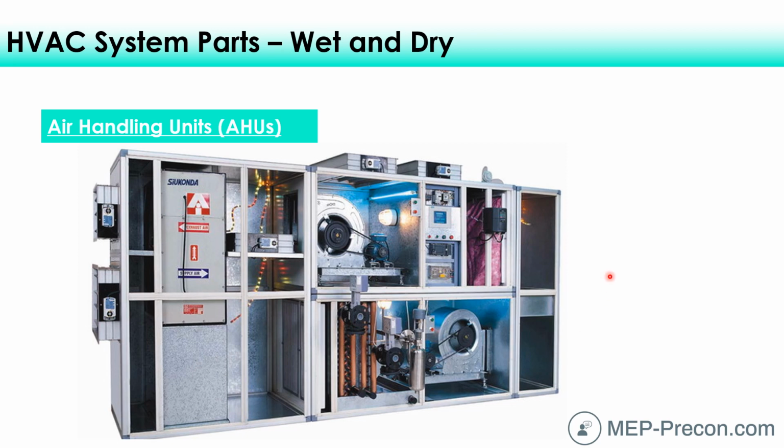Okay, and so all of those parts that we've talked about here get put together within an air handler. So now we can kind of see how all of those parts fit together within a system here. And so here we have a couple of fans, and this is a pretty complex air handler. So in this situation, we have a fan here that pushes air through what looks like a heat exchanger, maybe exchanging heat between the outside air and the exhaust air. And so the supply air could come in down here and get filtered, maybe goes through this coil and gets tempered.